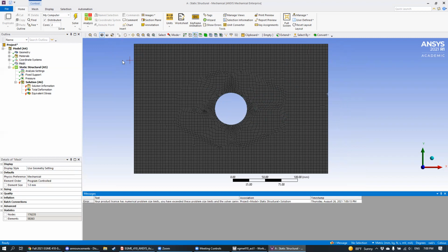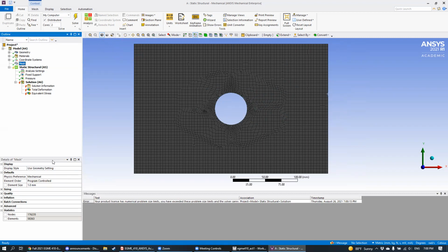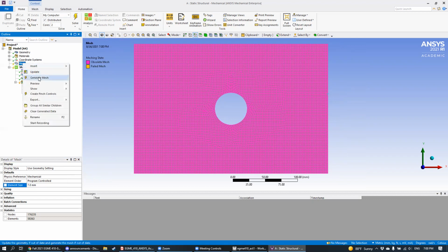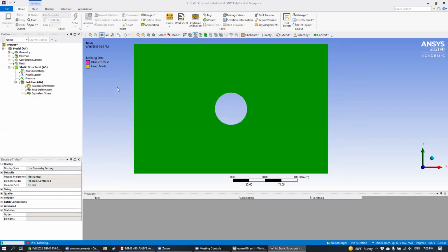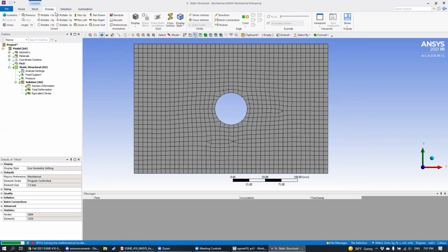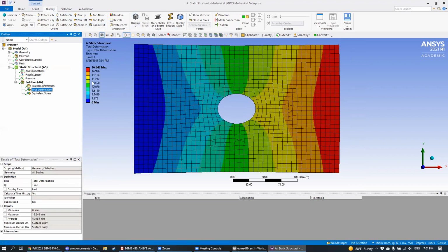One other question I had is that I noticed that if I'm not clicked on mesh, I can't see my mesh. Is there a way to have your mesh constantly previewed? Yes. I think it's under display here. So let's say we go to deformation here, and you go to display. And if you click on, I think yours might be, oh, hang on.